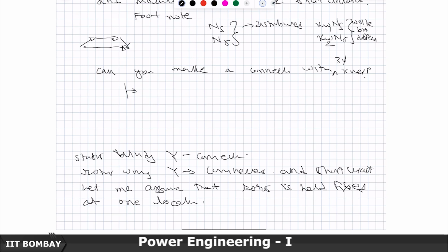You could connect those connections through a resistance, or you could have a connection going into another supply, doubly fed and all that. That is for later discussion, not for now. For the first discussion, these 3-phase windings will be just short circuited. So, you do not have any access to the rotor, you just mount 3-phase windings on that and short circuit them.